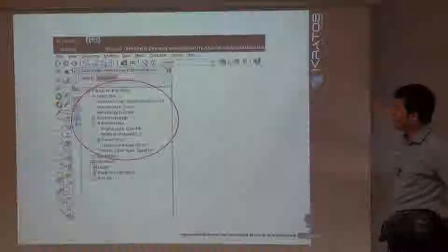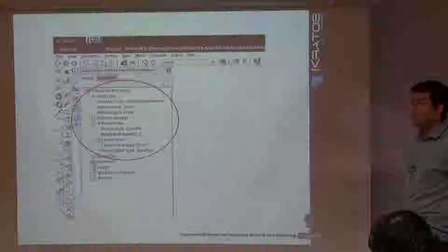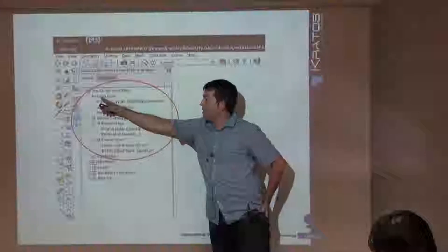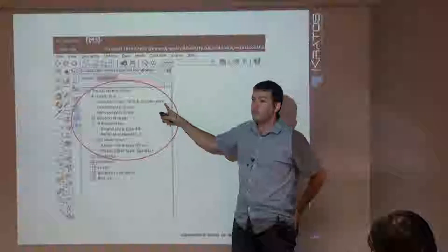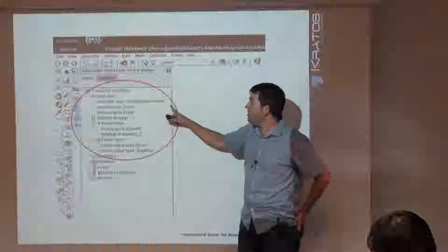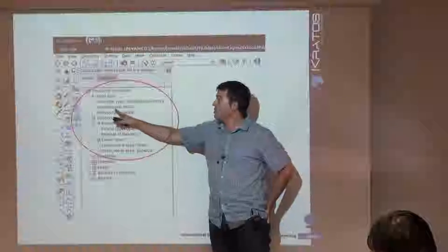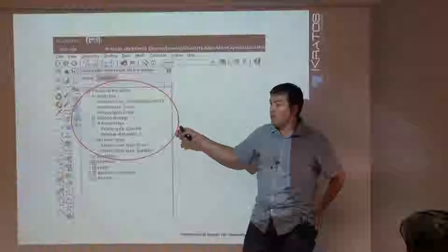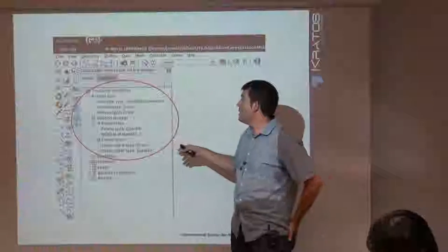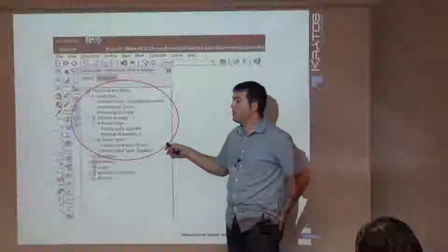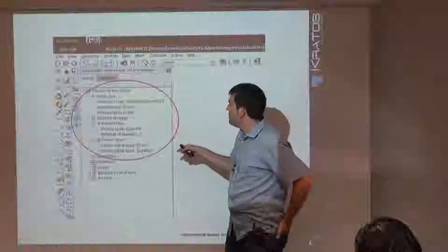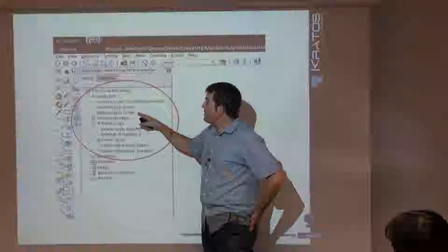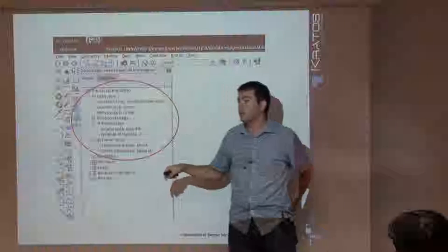So we start with the most simple example, and the most simple example is to use in the analysis type small displacements. Small displacements or large displacements are available. The solution type that we have selected is a static, can be a static and dynamic, also quasi-static, and also there is another type for membranes that is a type of dynamic thing. So solution type we selected a static and analysis type linear, right?